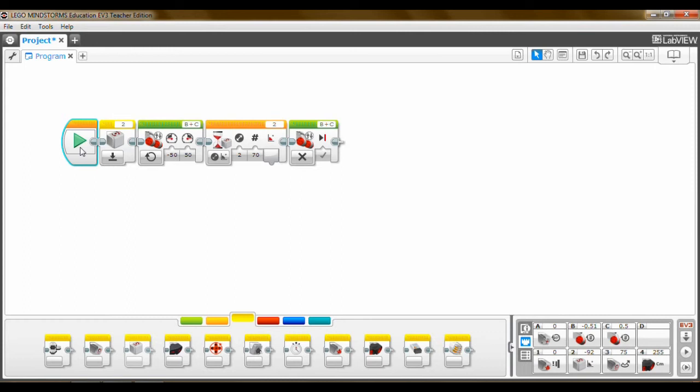Make sure that each time you make a turn with the gyro, what you change is the angle you're looking for and not the power the motors are using. If you change the power, it will be different than if you change the angle. So for every turn you want to do, pick a power and stick with it, and then change the angle. Experiment with the angle, and you'll be able to hit any turn that you would like or need. And that's all for gyros.